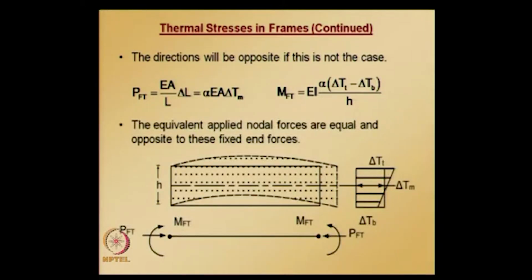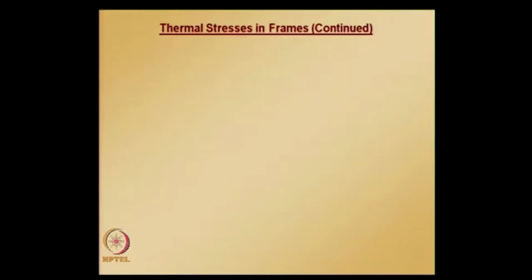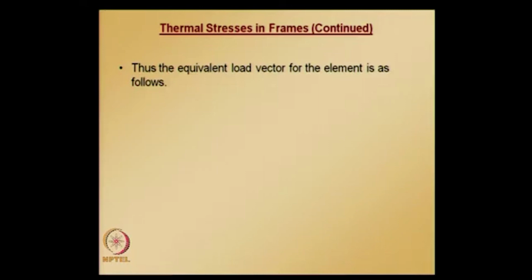Once we have this, equivalent applied nodal forces are equal and opposite in direction to these fixed end forces. So, we can easily assemble the equivalent nodal force vector. This equivalent nodal force vector for the element is given by this.